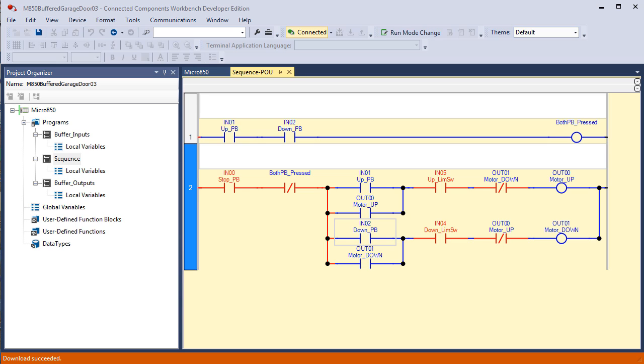So what we did was, first we had if up and not down, if down and not up. That didn't work. I mean, it worked in a sense, but if we let go of the buttons, it was still moving. We wanted to make it irritating for the operator if they were monkeying around with the buttons, trying to do up and down at the same time to see if they could do something to entertain themselves or even break the equipment so they could take a break, or they call maintenance. That didn't do what we wanted, so we added it over here.